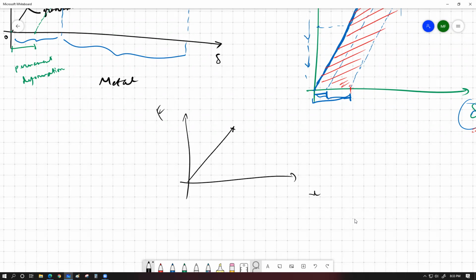So they have a straight line and then they cut off, or maybe they have a little bit of curve at the end. So it's also sometimes possible that they might have this and a slight bit of curve and then they break off. So brittle substances have little or no, I mean, they don't have any plastic region whatsoever. They might have a little bit of curve or no curve within their stress strain graph or force extension graph, but they are going to break the moment they are about to go into plastic deformation. Glass pieces never undergo plastic deformation, period.